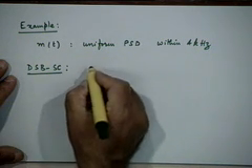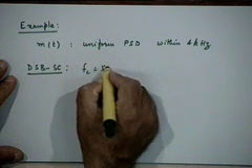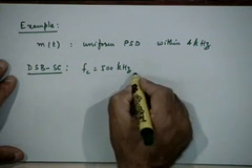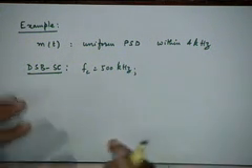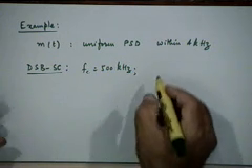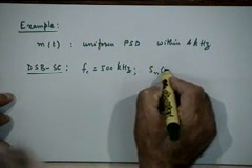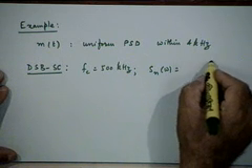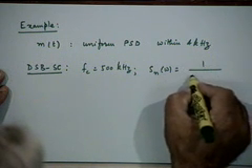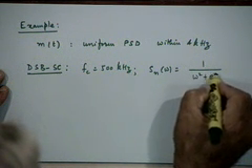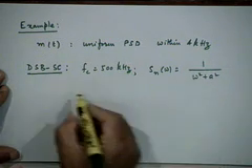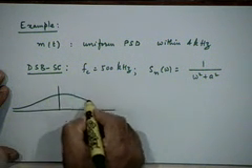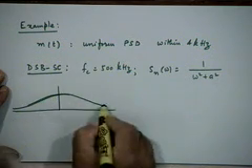Okay, carrier frequency is 500 kilohertz. Just some figures. And let's say noise is not white, but colored, which means it has a non-flat power spectral density function, and that is given by 1 by omega square plus a square. Okay, so we are assuming the noise power spectral density function to be something like that, right?